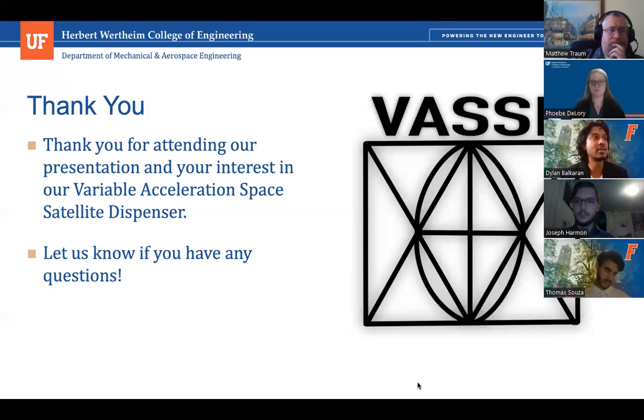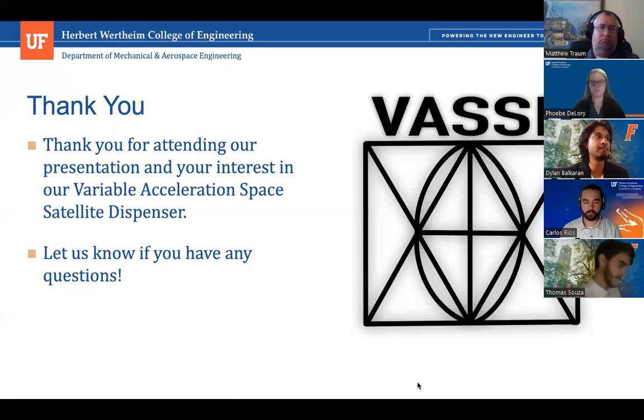So weight was a big factor. We did do a cost analysis on it as well, because we did know manufacturing would have been a big deal. I think Carlos could speak on that because he did a lot of the cost analyses for manufacturing processes. We did do a Boothroyd and Dewhurst handling and installing time for assembly. And as for manufacturing, we were considering the overall price for equipment and machining or for tooling, as well as labor. The main labor that we considered for the gussets involved mainly the bandsaw as well as the CNC machine.